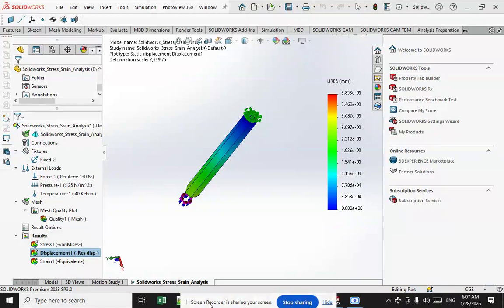For parts that have broken in service, a forensic engineering or failure analysis is performed to identify weakness, where broken parts are analyzed for the cause or causes of failure. The method seeks to identify the weakest component in the load path. If that is the part which actually failed, then it may corroborate independent evidence of the failure. If not, then another explanation has to be sought, such as a defective part with a lower tensile strength than it should have, for example.